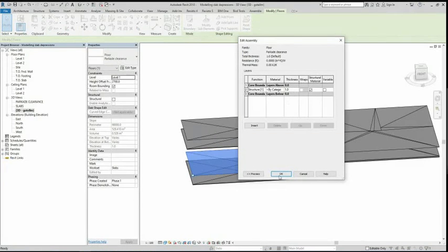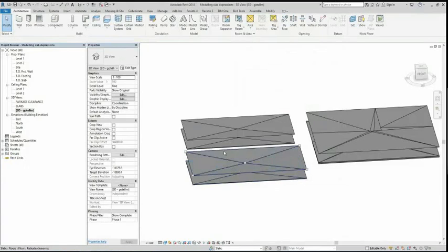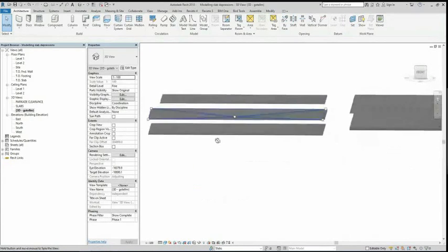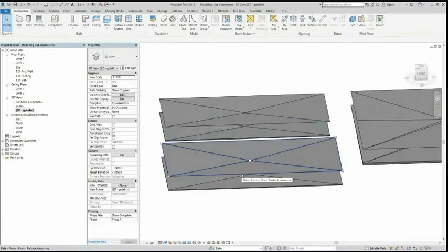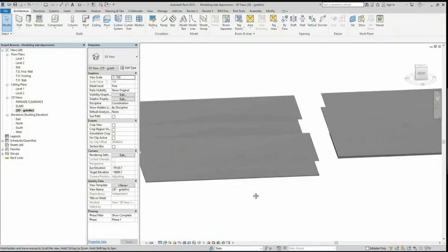What I've done is I've set that to 1 millimeter. So that should be good. And you have a floor depression with a parquet slab clearance, or a parquet clearance or service clearance. And the nice thing is when you copy these elements and paste them, it basically follows the profile of the floor slab that you just modeled. So anywhere along this area or footprint, you have the same clearance no matter what.